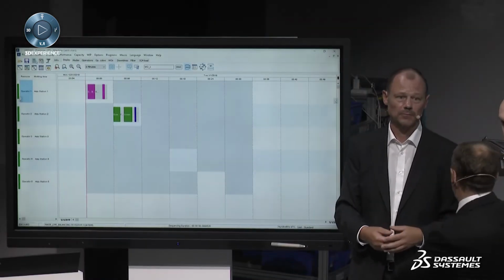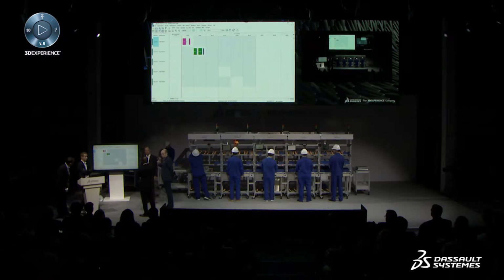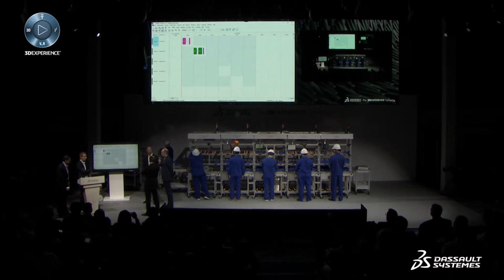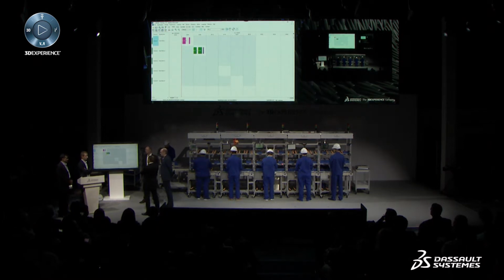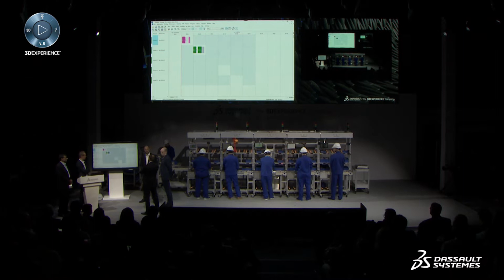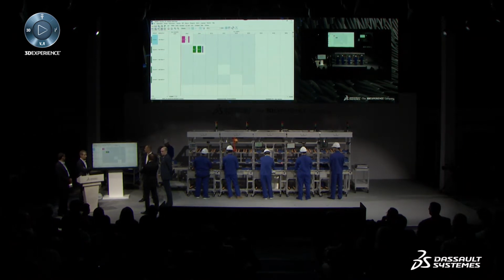Okay, so that's good and bad news. Let's say that you double the takt time, so we decrease our throughput basically, which is not good, but we still can produce, and we will use fewer operators on the line. Okay, so for me, it looks good.